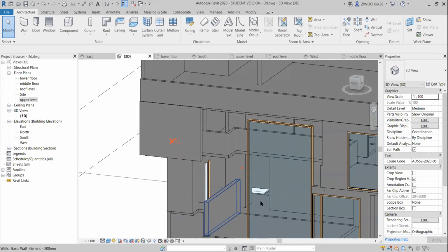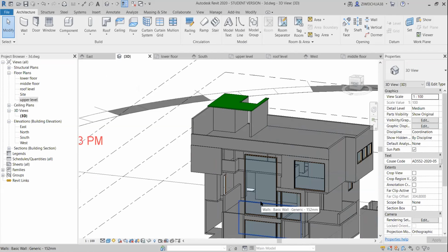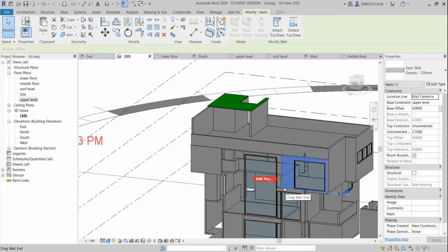Maybe you still need to see the end of the video in CN regarding window modeling, because I explained how to model. You did it already, but you still have problems. For example, here there's an opening. I can see inside, as you can see. So basically, this wall, you have to move it. You have to edit the boundary of this wall. Okay, later I move it. So this wall, you have to move it until here. So you have to edit the boundary. I think you know how to edit the boundary because now there is an opening. Oh, okay. You see the opening, right? It's here, the opening.